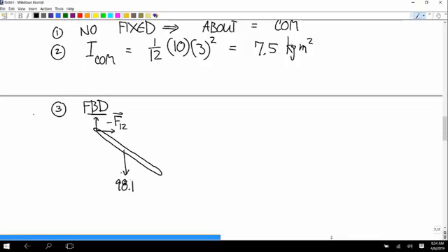And then at C, we have this pin and slot joint. There's the slot, and the force is perpendicular to that. There's nothing restricting motion this way, so there's no force. It only restricts motion. You can draw that force whichever direction you want. I guess I'll put it in the positive x direction. That variable can come out positive or negative. I'll write that as the scalar RC. And then rho vector, force vector, moment vector.